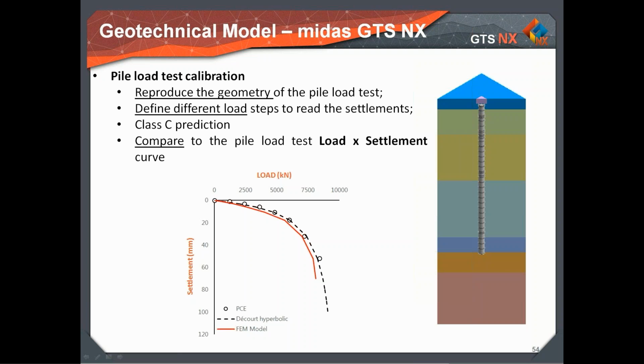The load-settlement curve shows the pile load test result along with the finite element model created, and the values of settlement seem to fit well to what was measured.